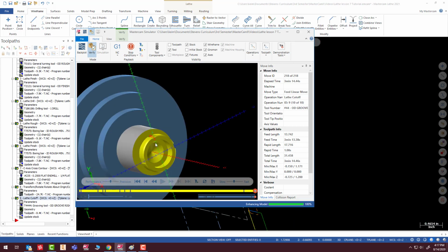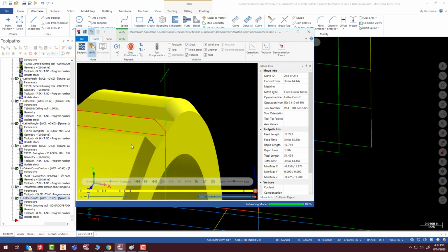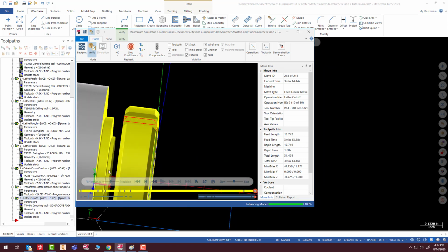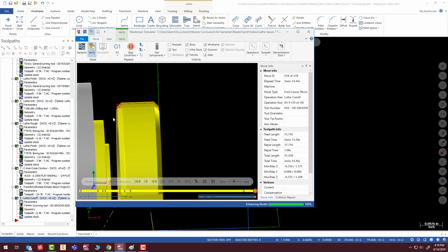For this one, I might not, though. Earlier when I said I'd do it that way, I wasn't really thinking about these grooves being in here. The cutoff tools aren't very rigid usually. You could probably get away with this because it's aluminum, but generally, if you have an interrupted cut, it's going to cause some problems here. You want a nice sturdy tool to put that on there, and plus we were putting it on there with a finish tool before we even put those grooves in, so that would look much better. I think that the way the book does it is probably the best way for this part, but this is another way you can do it. So I just wanted you to know how you can put the chamfer on there. This is great when it's not an interrupted cut.